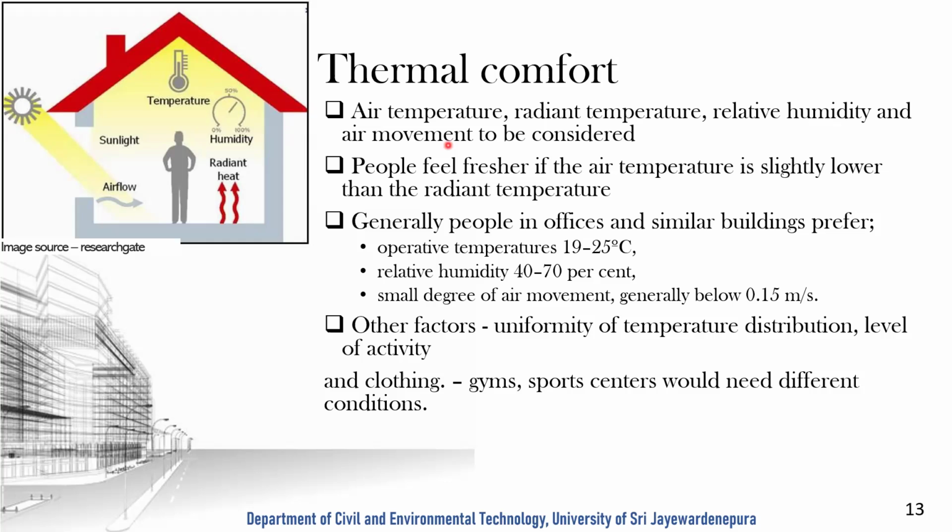Now, generally, offices maintain operative temperatures of air conditioners or air controlling systems at 20 to 25 degrees Celsius. Then relative humidity 40 to 70%.